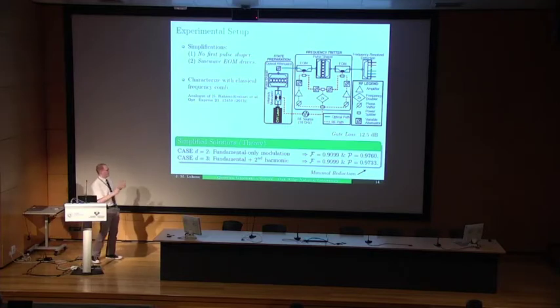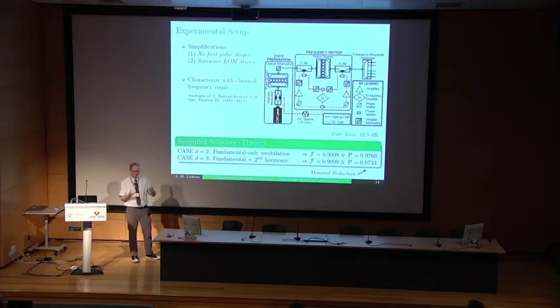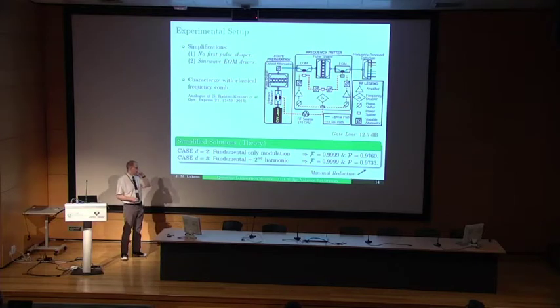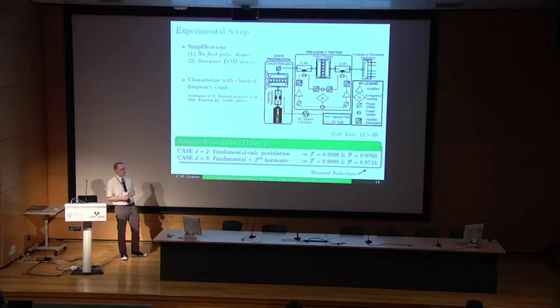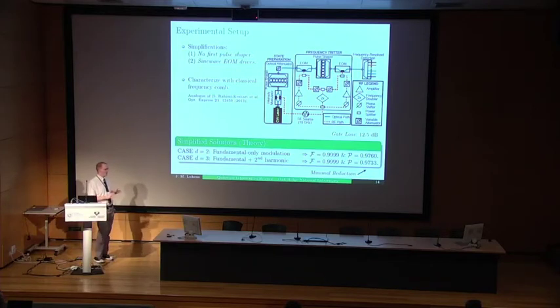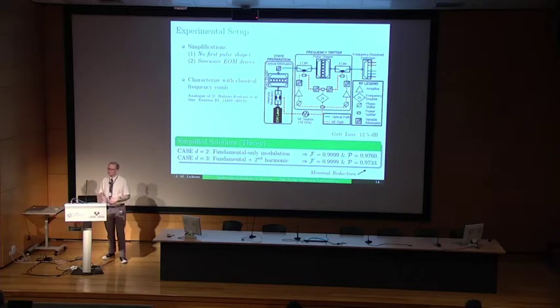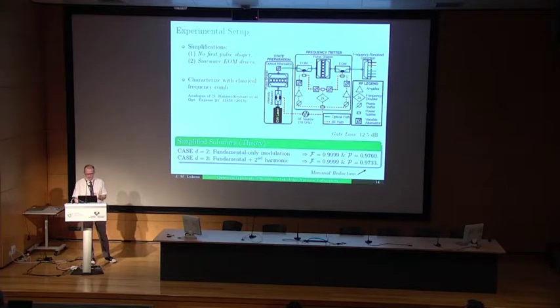Oh, and I will point out the main disadvantage of our approach currently is that we have high loss. So the gate loss right now is about 12 dB, and this is because we're buying off-the-shelf telecom components. So they each have a few dB loss per component, but we think this can be significantly reduced, although it will take some important engineering. I will emphasize that the loss is not intrinsic to our method, so the operations that we're implementing are phase only, they're unitary. So this is just an insertion loss, a technical issue, not fundamental to the method.